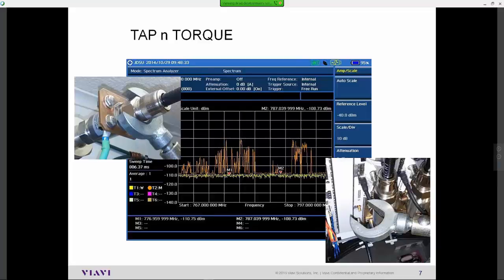Both of these are examples of placing your transmitters into test modes, where you have settings that allow you to push the transmitters to full power. And ideally, if you're monitoring your receives at that same time and you see a correlation where your receive levels increase, you can clearly determine that you're dealing with interference that's self-inflicted.